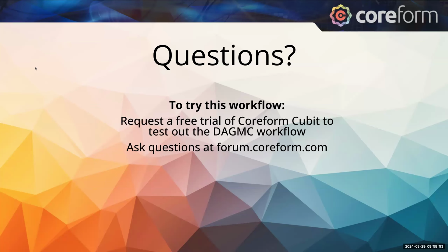I think, especially for OpenMC and for most codes, it's really better to try to specify those tallies as part of the native input pieces. So in OpenMC, what I can do is specify a cell filter, which would be analogous to filtering out a specific volume that I want information about within the DAGMC model and apply it that way. I think that would be my recommended approach at this point in time.